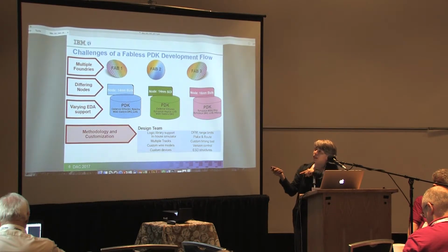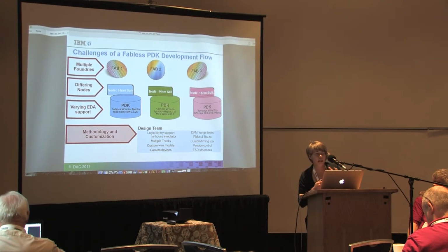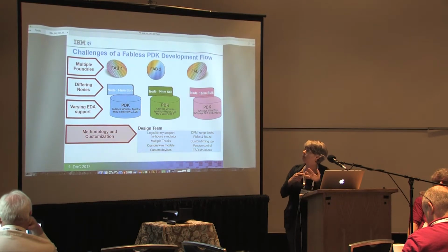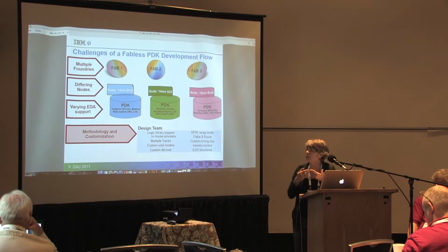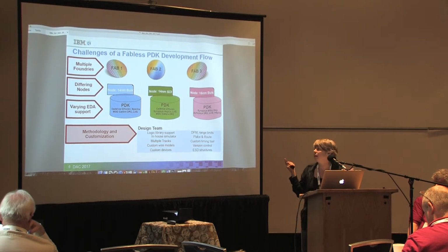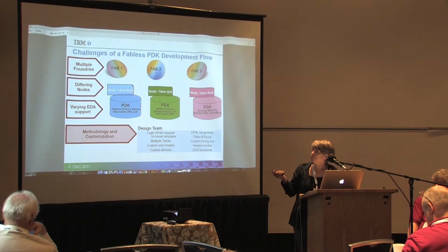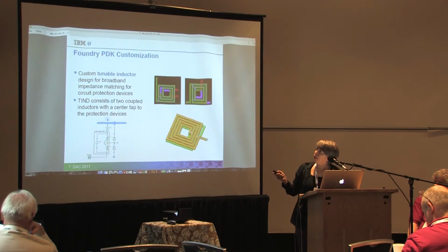And there's varying EDA support with each one of these fabs. One may be a Mentor house, one may be a Synopsys house, one may only support HSPICE models, one may only support Spectre models, one may just support K-layout. And then there's methodology and customizations that we do on all of our tools. So this customization is also on the product side.